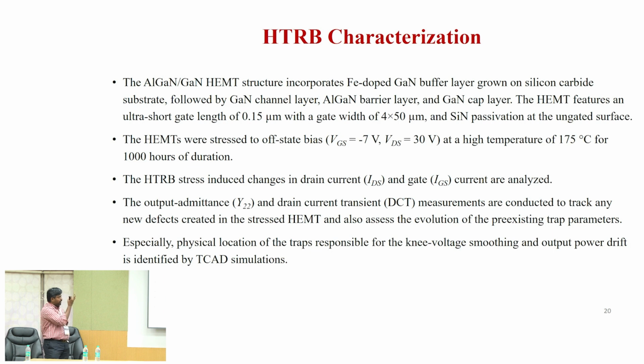So even if you are having a cryogenic probe station, you can do this measurement, because in a cryogenic probe station you can operate your device in vacuum condition. So your devices will not be affected by the humidity or storage conditions. So even with a vacuum probe station also you can do this kind of measurement.